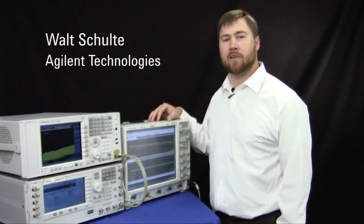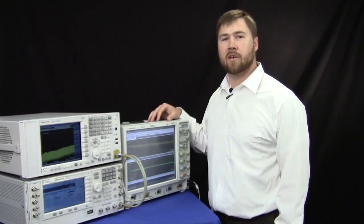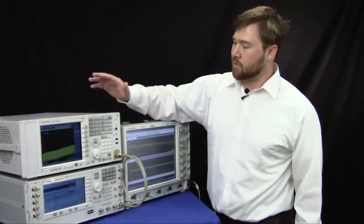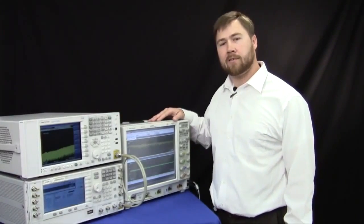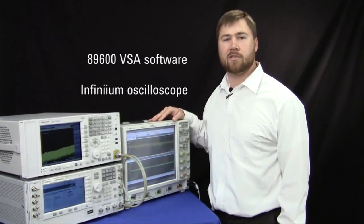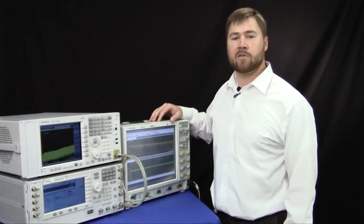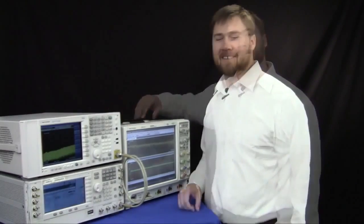Today I'm going to demonstrate a cost-effective solution for measuring wideband radar and SATCOM signals. To do this, we're going to use the PXA as a wideband down converter into our Infiniium oscilloscope using our N9030A vector signal analysis software. We're going to use a source to correct the amplitude flatness of the IF.